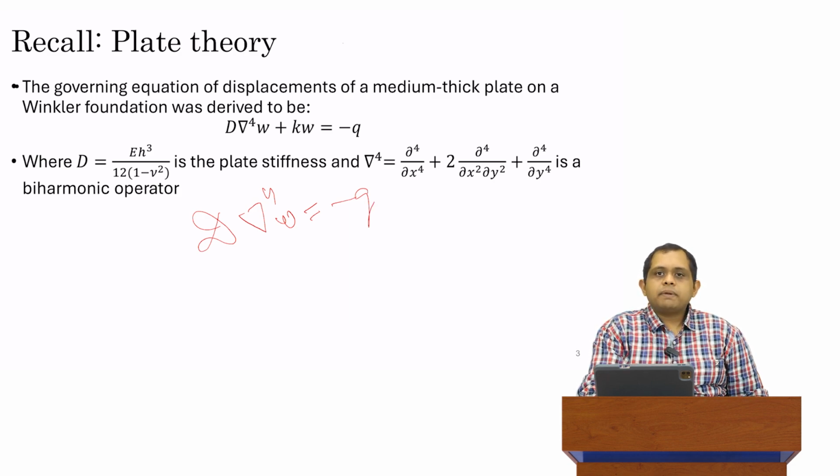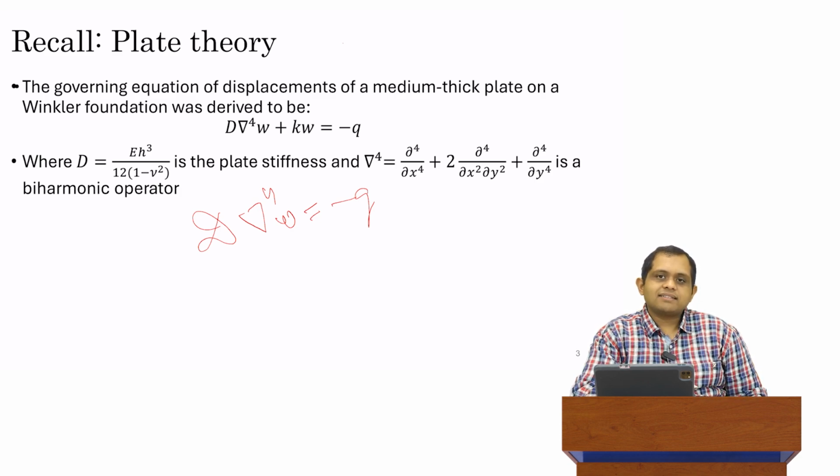As a reminder, a plate is a special type of structure, or rather, we are looking at Kirchhoff-Love plates, so medium thick plates. A medium thick plate is a special type of structure which, in addition to being linear elastic, isotropic, etc., follows two additional assumptions which are not made in general layered elastic analysis. Those assumptions being that we do not admit shear strains.